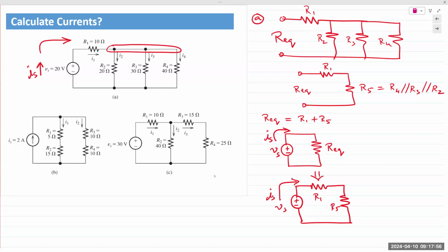You guys with me so far? And then if the current is going in this direction, which side is plus and which is minus for R1, left or right? Left is positive. Point of entry for a resistor, for a passive component, is always positive.